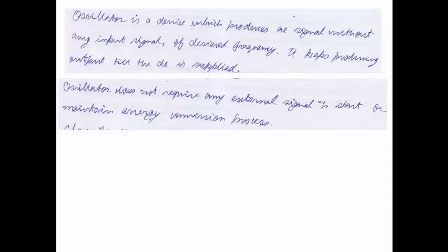So what we are doing is trying to apply positive feedback to the existing noise within the oscillator. Noise is omnipresent. We should always keep in mind, all the time to come, that noise is everywhere. In all other cases we try to suppress it because it acts as an undesired signal, but this is the only place where we would like to preserve it, so that it gives us the specific alternating waveform or alternating outlook to the signal.